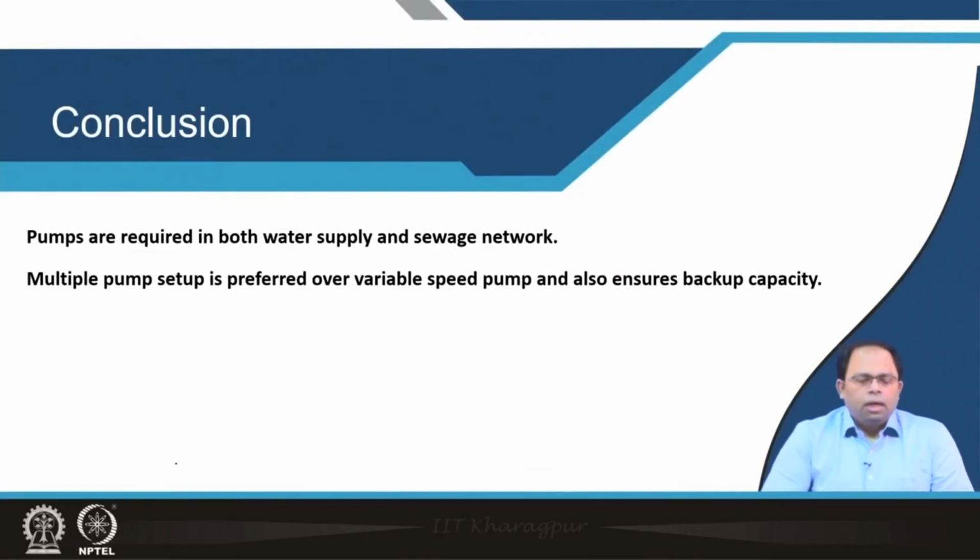To conclude, pumps are required in both water supply and sewerage networks, and a multiple pump setup is preferred over a variable size pump, and this also ensures backup capacity.